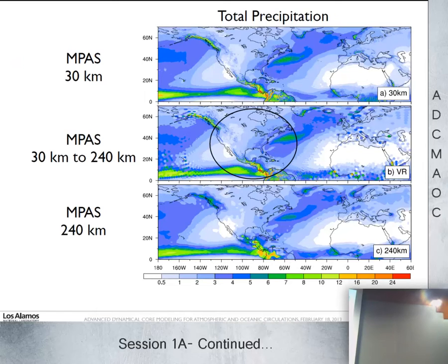That has to do with the fact that I made a mistake in how I'm integrating my dissipation term. I'm pairing my dissipation term with an RK3 method, which is a bad idea, right? So this actually has nothing to do with the mesh, and has to do with a very basic numerical principle that I overlooked.